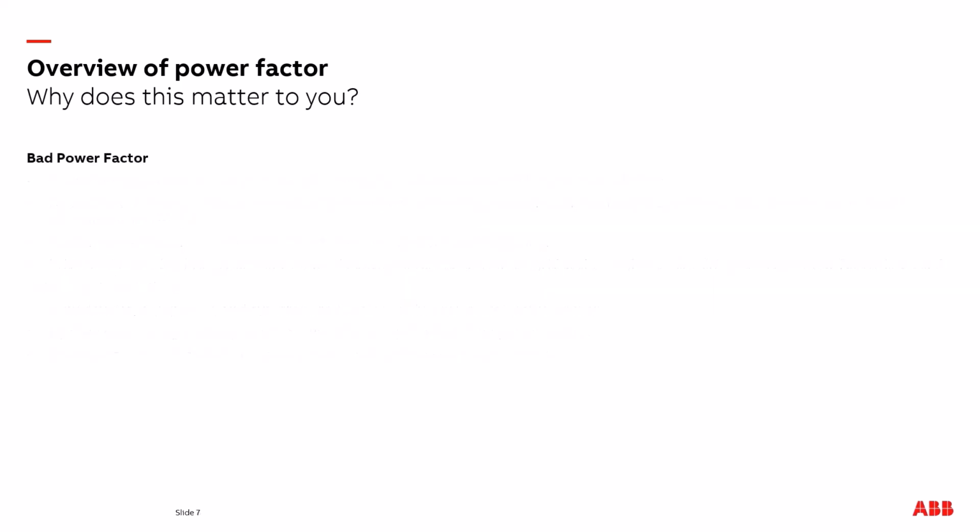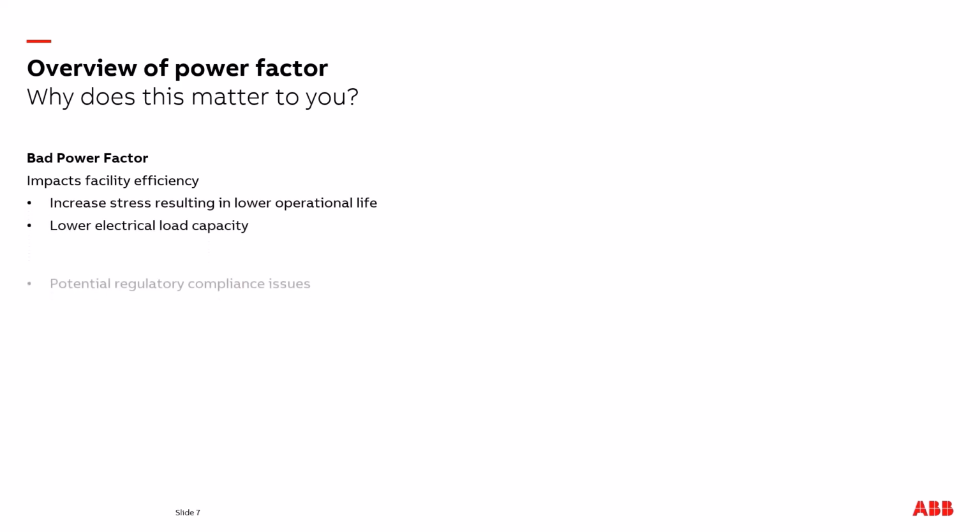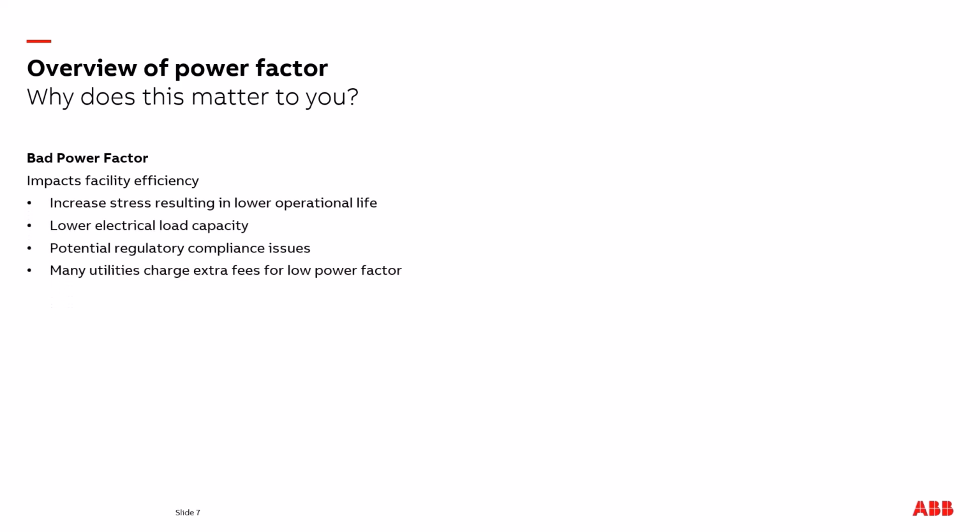Let's take a look at what bad power factor does to you. It impacts your facility's efficiency. It increases stress, resulting in lower operational life of your equipment. Lower electrical load capacity is created. Potential regulatory compliance issues can happen. Many utilities charge an extra fee for low power factor. It has an environmental impact because more fuel is burned at the power plants, causing higher greenhouse gas emissions.